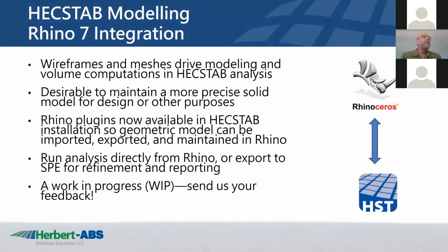So wireframe meshes do drive the modeling process, but if you're in the design world, especially, it's really desirable to maintain a more precise solid model with real surface modeling capability, so that the surface is fully defined. When you have a station model, you're just doing cross-sectional cuts in certain locations, and that's not sufficient for many other uses if you're in design mode. And it's also difficult in many cases to model things with stations, especially in the offshore world.